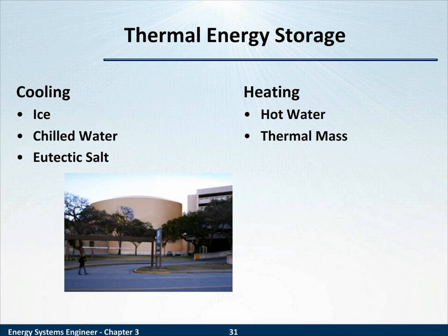If you have spikes because of air conditioning and peak time and demand charges, it can be economically beneficial to reduce those spikes. Again, you're not changing consumption. You're just saying, you know what, I will chill my water at another time, at a time where I'm not in a demand cycle. So thermal energy storage works with either cooling or with heating.